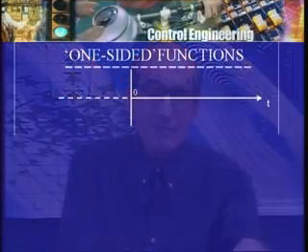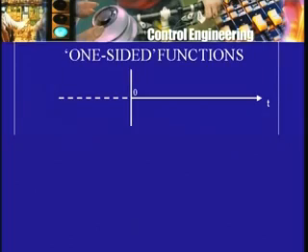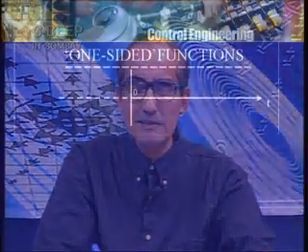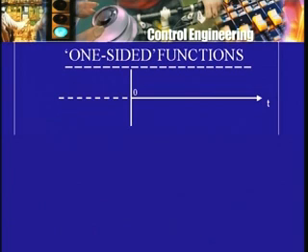Now, these properties have to be understood properly. First of all, recall once again that the Laplace transformation transforms one function, usually regarded as a function of time variable, into another function. And one more thing, I mentioned that in control we are interested in the values of time greater than or equal to 0, and therefore such functions are called one-sided functions. We are interested only in one half of the time axis, starting from 0 and going on towards the future. I have been showing it like this. This is 0. We are not interested in the other half, but it is possible.